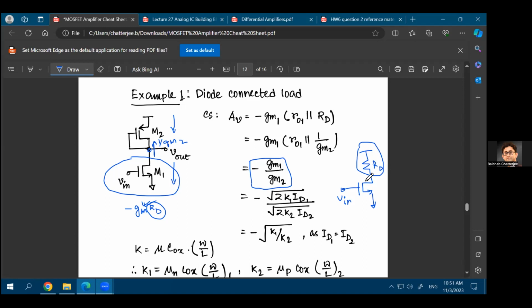So instead of using this resistance, you can use the MOSFET, which is again a very tiny structure. Instead of this resistance, which could be hundreds of micrometers long or wide, you can use a transistor, which could be, let's say, just a micrometer long or a micrometer wide. So that's the advantage of using a MOSFET over here instead of the resistance. Okay.